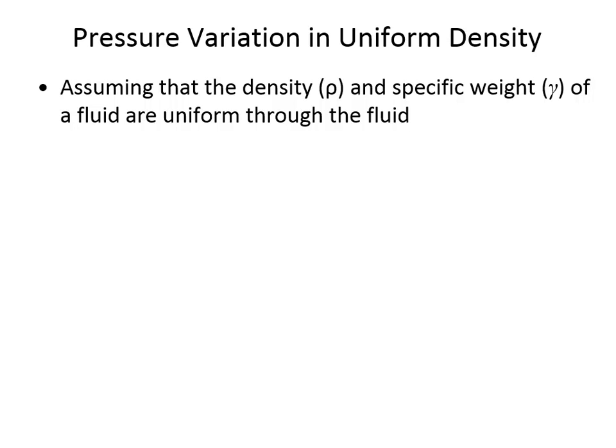Now there are some considerations here. We assume that water has uniform density as we move up and down through a column of water or some other liquid. It's not always water. For liquids, that's a pretty good assumption, but for gases, it's not the best assumption because remember earlier today I said that the pressure at Mount Everest is lower than the pressure at sea level. So air is a fluid.